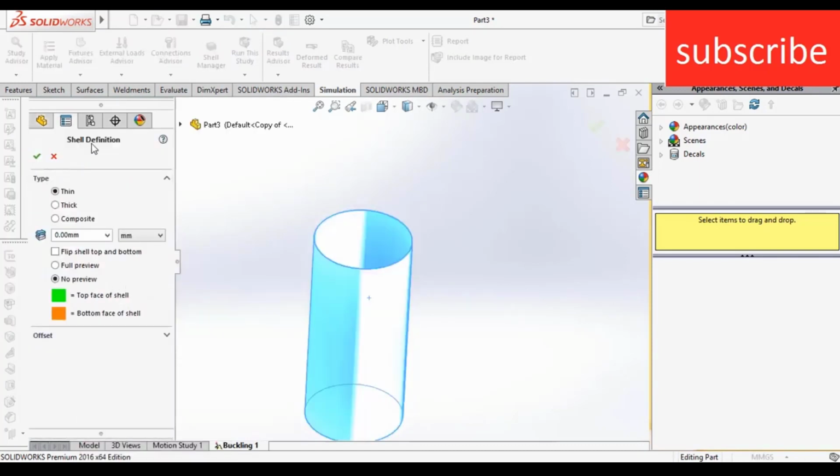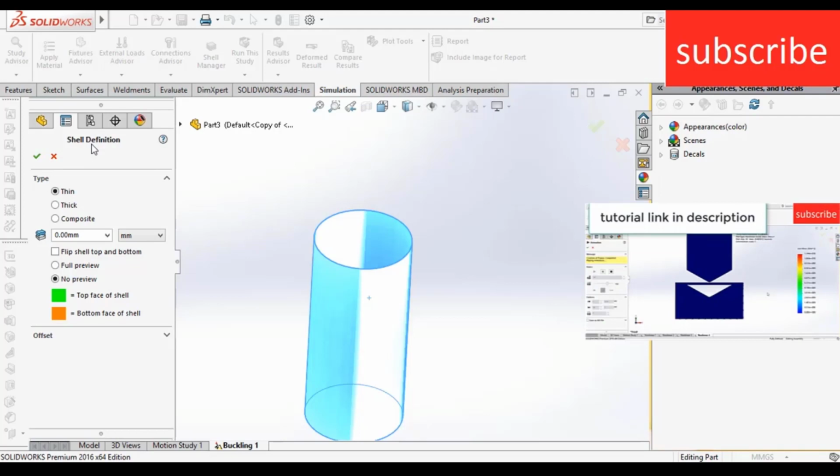Now the first thing we need to do is right click on it, click on edit definition. Basically where I am is shell definition. Now let's learn why, where and how to use shell definition. Shell definition is basically used when we're talking about very thin objects, for example plates or things that are less than 5 mm or below 10 mm.